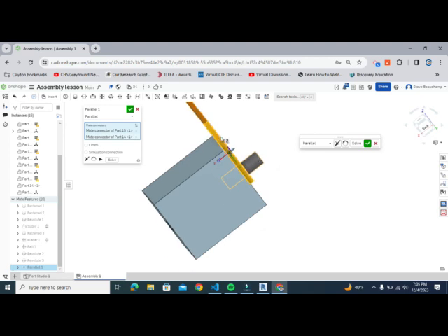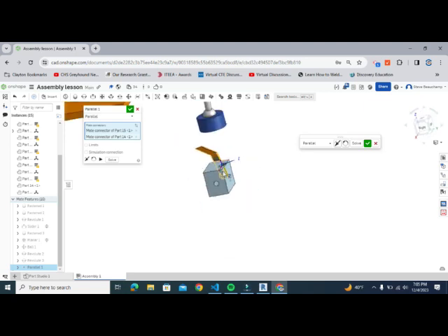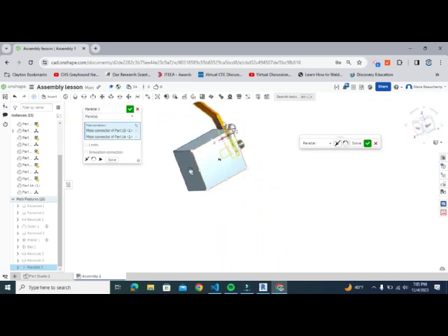And essentially what it's doing is it's not really worried about the revolutes that we put in. It's worried about the parallel, saying, can I make those two things parallel? And you can see that they are. Okay, but if you want to check all of it together, you can hit this little solve button and it'll check it and say, yep, we can make those parallel and we can use the revolutes.